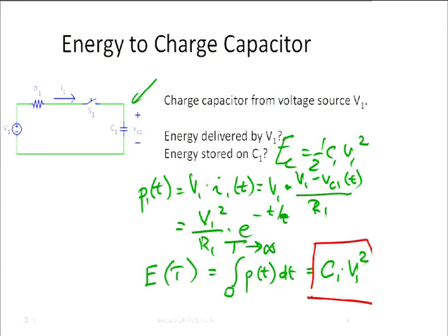If we use some kind of lower resistor, maybe an ohm or so, then still, apparently according to this equation, we lose half of the power in the resistor, and only the other half of the energy actually ends up on our capacitor, right? That's a bad thing because, for example, if this is some kind of toy, over here is an alkaline battery that we paid good money for, and over here is our capacitor that's in the toy, in that little helicopter, whatever it is, that we want to fly, and we want to charge it, right? And half of it is somehow burned up in that resistor.